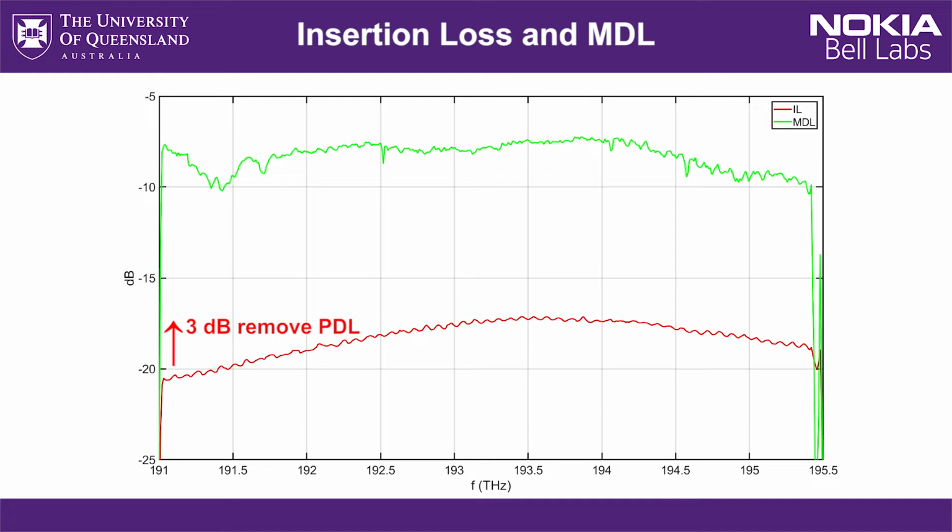You could potentially make the multiplane light conversion system with dielectric reflections instead of gold. That would buy you another 2. And then optimizing the spectral pulse shaper itself would get you down another 4 dB for a total of about 8 dB total loss. A more optimized device should be capable of something around that. And of course, chipping away at losses in your design and build is a game that you can play from now until the end of time, right?